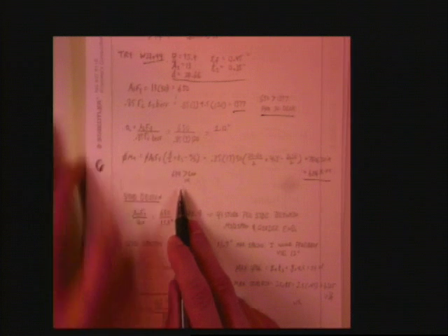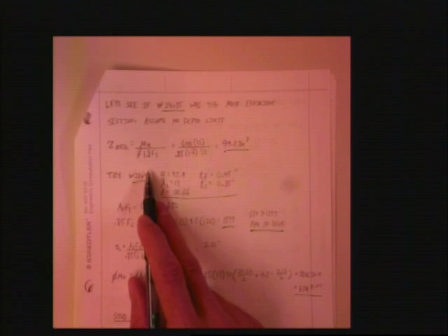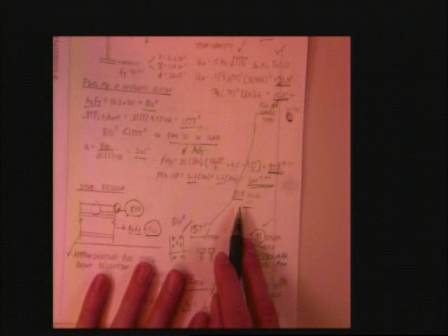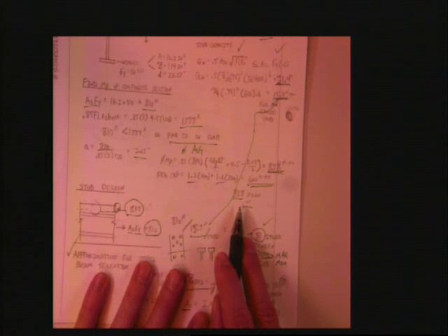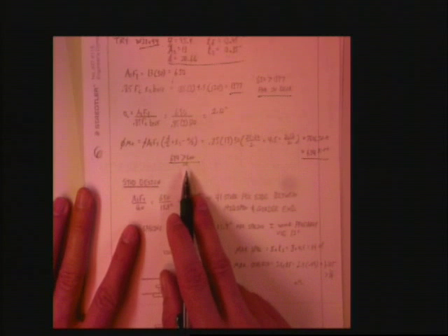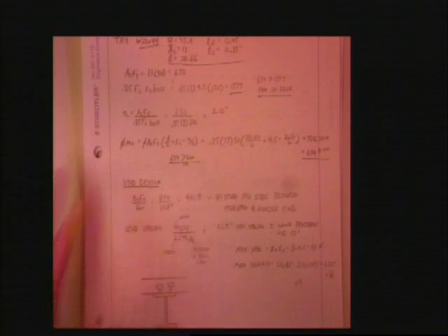And this equation wasn't just made up. It was derived, and we'll talk about how it was derived coming up once we get to plate girders. But what I want you to realize is that with that other section, we provided 858 kip feet. Way more than we actually needed. And with this equation, we're able to provide 634. That's like 5% more capacity than what we needed. That's awesome.